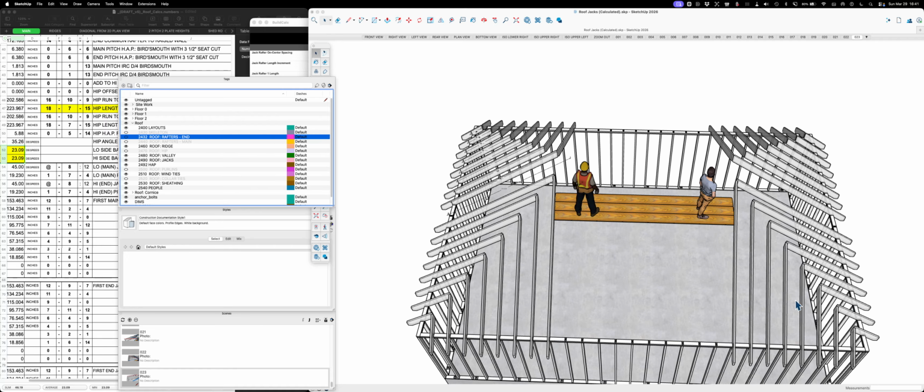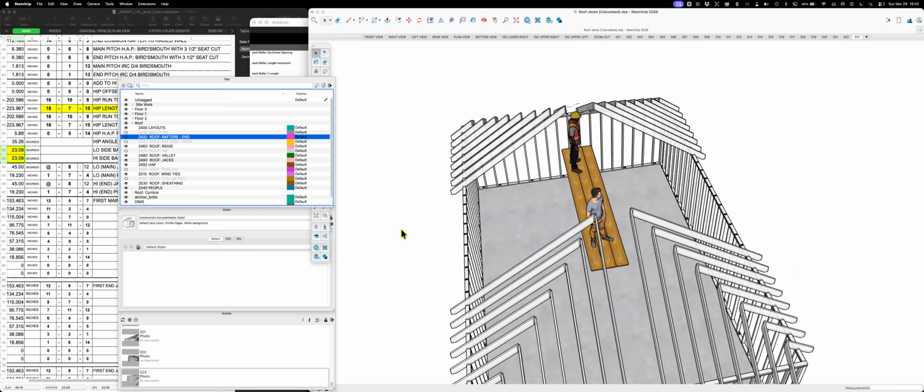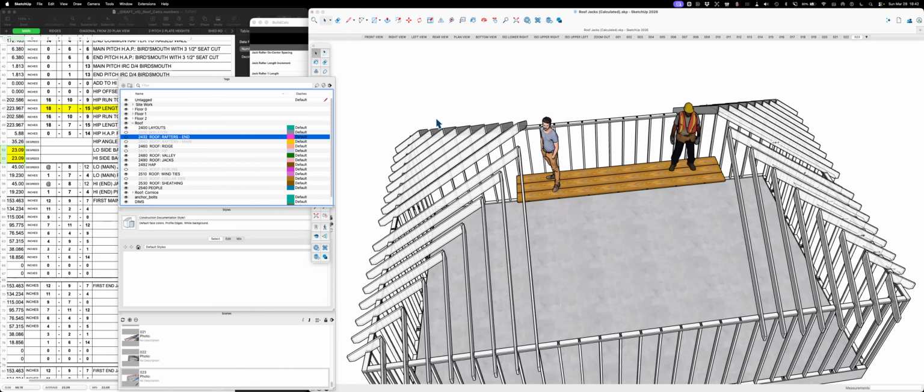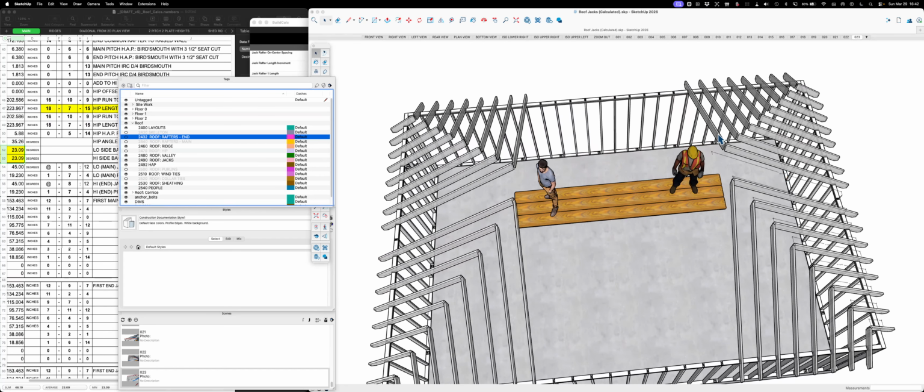But you're going to get a building that's an odd size, and there are people out there that they'll start on their boss corner, wherever that is. Here it is. And then as they do the rafters, everything here is breaking 16-inch, 16-inch. And then right here, they will start their jacks 16 inches past the last common rafter and recalculate all this stuff so that it's continuous, 16-inch all the way across. And the only reason they do that is to save 2 rafters.